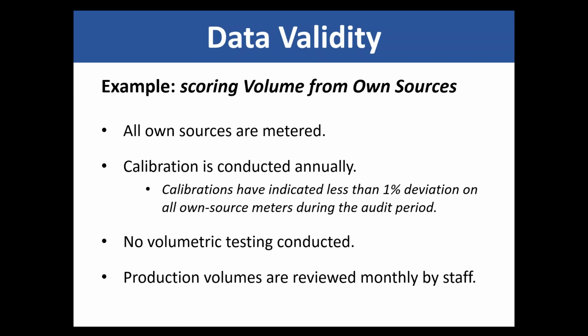They do not conduct any volumetric or comparative testing. They don't draw down a reservoir and compare how that volume looks against the meter register. They don't stick an insertion meter in the pipe and compare that to their meter. They also review production volumes monthly, looking at SCADA, looking at meter reads, and truing everything out. Given this circumstance, we now want to put them onto the data validity scale for the volume from known sources.